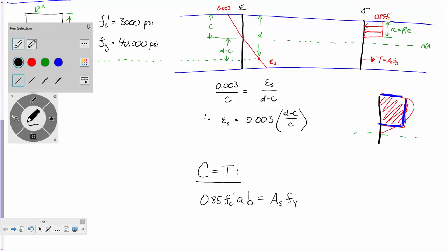That make sense? Now, we know that f'c for this beam is 3,000 psi. We know the beam is 12 inches wide, and we know the area of steel. Well, let me ask you this. Let's talk about the area of steel. What do we have in this beam? What is it? 3 number 9. So, first page, we have our ASTM standard reinforcing bars. We are dealing with number 9 bars. So what's the area of a number 9? 1 square inch. Remember that? Number 9s always made my life easier when making problems because number 9s were 1 square inch. So 3 number 9s are 3 square inches.